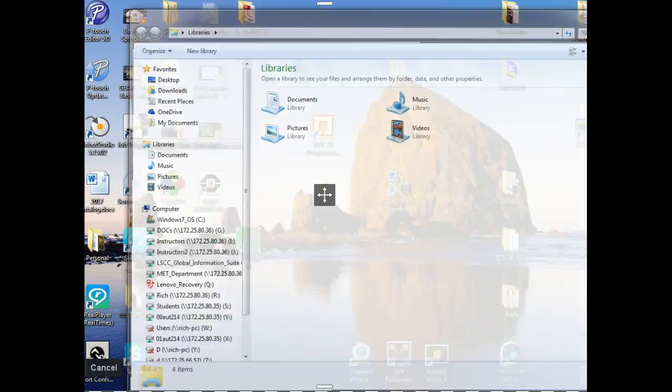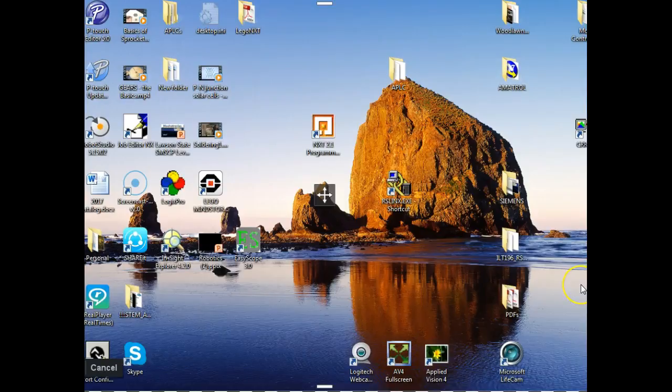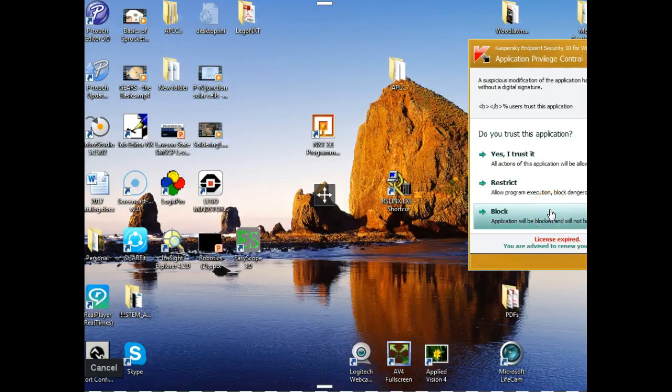And position too, right? So we can use it for quite a few things. This one right here, let's see how many slots we have in this encoder. Let's see. This guy's got 1, 2, 3, 4, 5, 6, 7, 8. So this guy's got 8 blades or 8 detectors in the encoder.